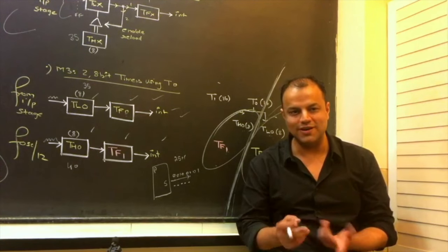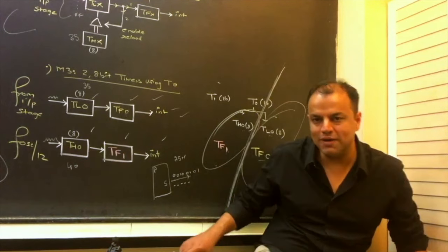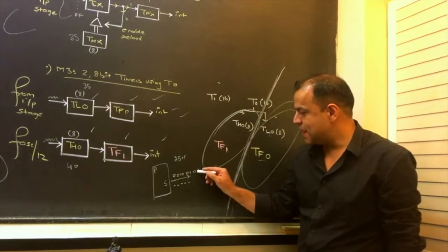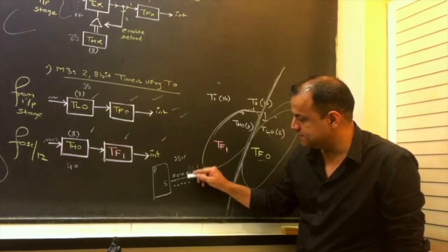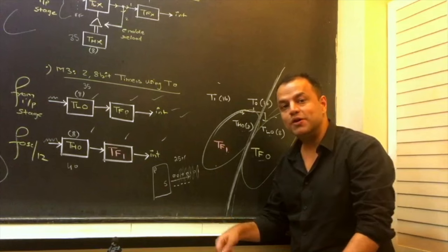How can you send 8 bits on one line at one time? The same line cannot be VCC and ground both together. So they will go out one by one. What does the word one by one mean? After every bit, there is a delay, a small time gap. Who produces a delay? Timer.